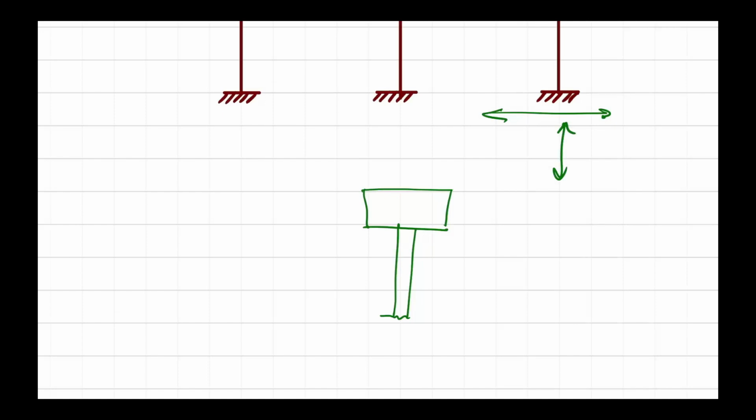And maybe for the piling, because you need to hammer the pile head. When you hammer the pile head, you have the stress wave going through. So you have the compression wave and then the tension wave, alright? So that is going to damage your pile. So pre-stressing also helps in these two aspects. But it is not designed to carry the moment under the service condition.